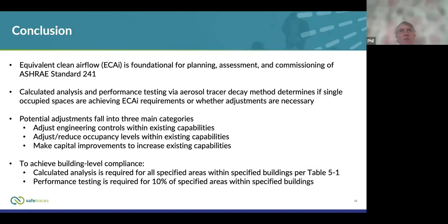Yeah, go ahead. So my mention of that was that the decay rate is a logarithmic decay rate, and the calculations are similar to those used for tracer gases. I did not intend to confuse the issue. We are using particle counts, and the decay rate of particle counts is evaluated using a logarithmic decay method to establish the volume of clean air that's coming in.